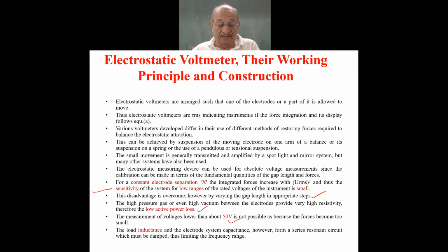Then the load inductance and electrode system capacitance, however, form a series resonant circuit which must be damped and thus limiting the frequency range. And this is a problem, the last one mentioned here, specifically in case you are measuring high frequency voltage, which is rare.